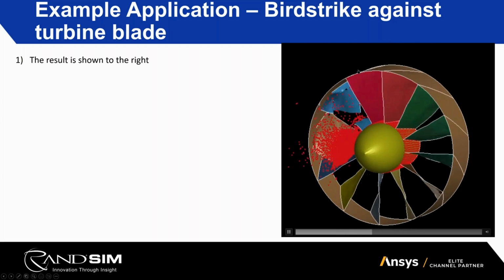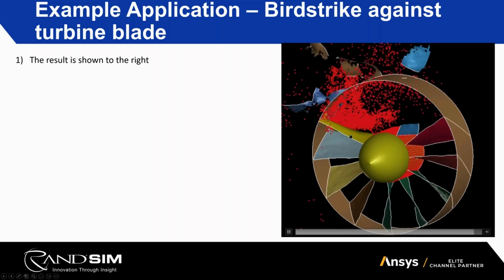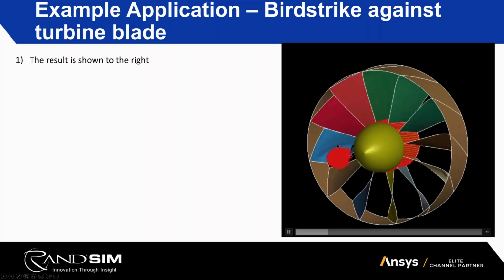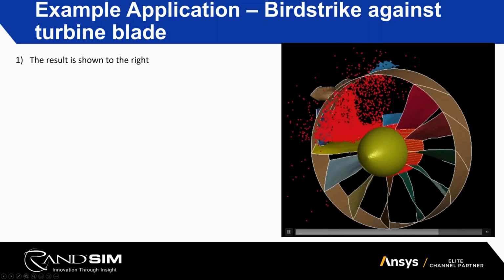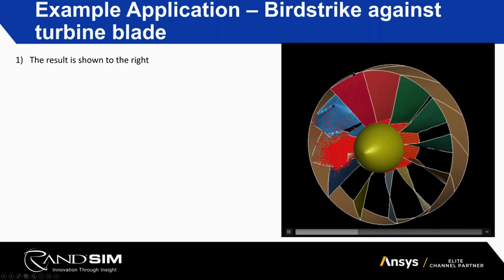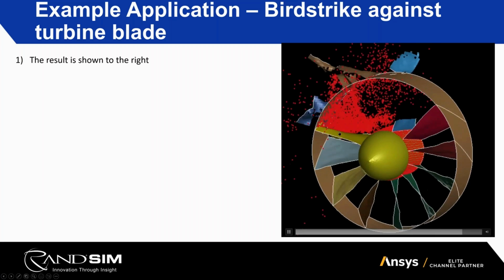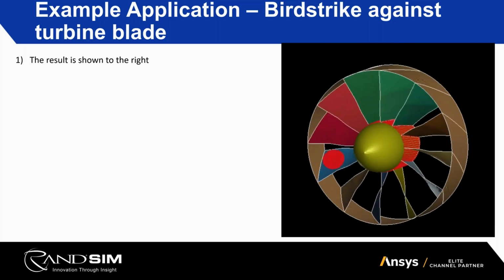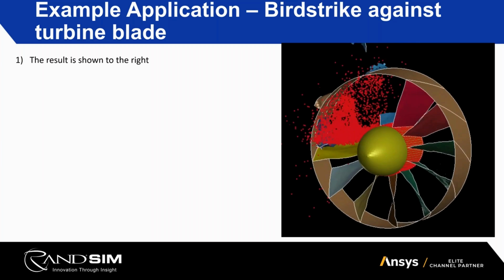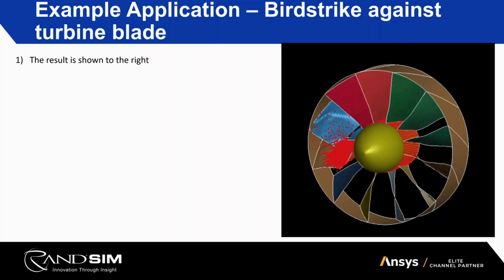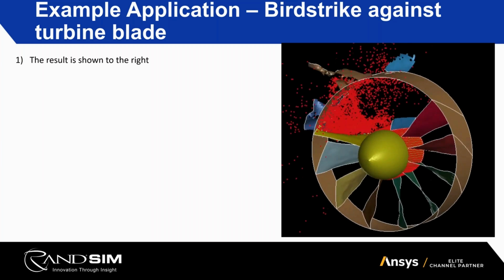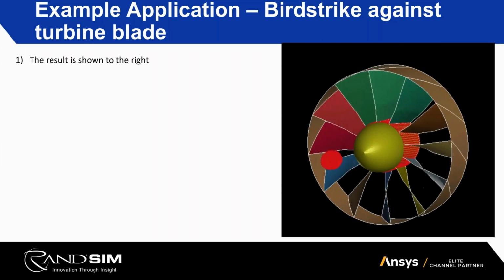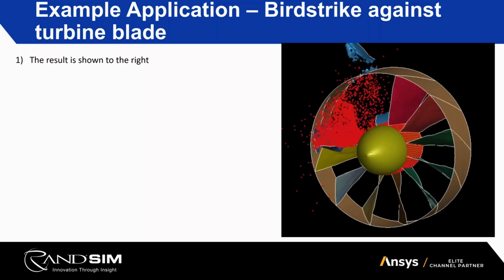Now, of course, I have some initial conditions here that I didn't talk about, but that's really the nature of a bird strike analysis, right? And because the bird strike shape and the material model for the bird strike shape is well-published information, we can use it for a much more complicated turbine shape, right? This turbine shape is made up, but we can do this kind of analysis for anything that's much more complicated in real life, right? Because the process isn't really changing. What is changing is the nature of the input parameters. Like we need to understand the structure, its stiffness, the material we're using, the way it's built together. But the modeling approach is the same as the simple model that I'm showing you here.